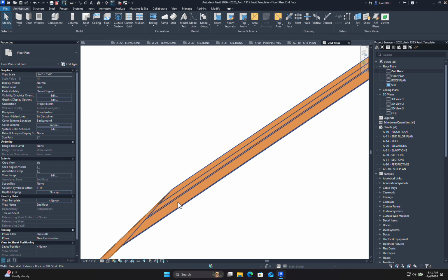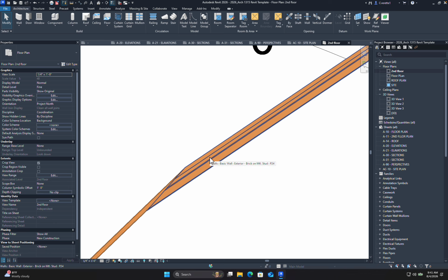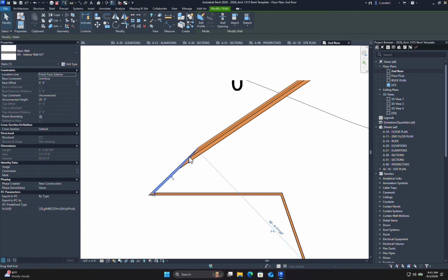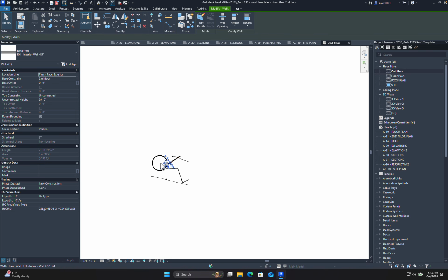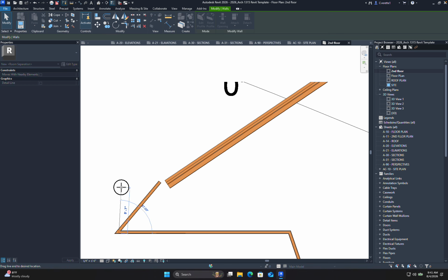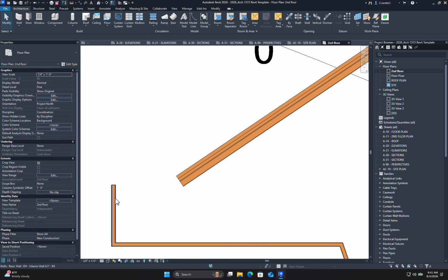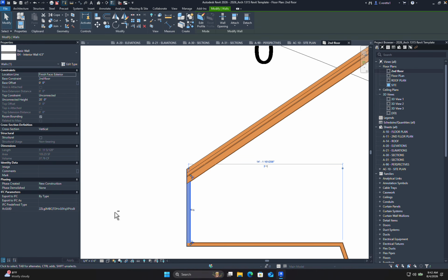In our case, we have the studs, we have the airspace, the sheathing, and of course like a brick or stone wall. And it is pretty nice that that was instantly drawn by just selecting a different wall type. For instance, now I could even change these wall types by clicking on these little blue balls, if you will. They're more like little nodes, but that is essentially the way that we control things in Revit. It is annoying I didn't make this program, but it is kind of nice to be able to still change things, right? But it is kind of locked into place, and as soon as I hit something, it's trying to help me out, a little bit, right?